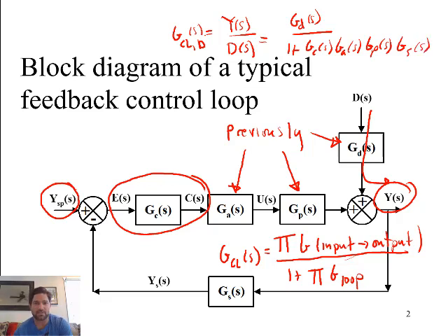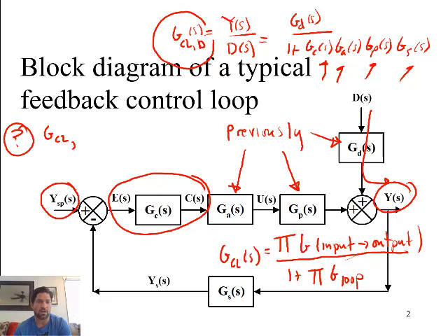Right, and so in order to determine stability, or the stability response, etc., of the overall closed loop process here, we need to know all of these individual transfer functions. And we kind of know these. We need to have these transfer functions and then rearrange, put into standard form, and then we can assess stability. Okay, what I want you to do, I'm going to pause on the side, is derive the transfer function for the overall process with respect to the set point changes.